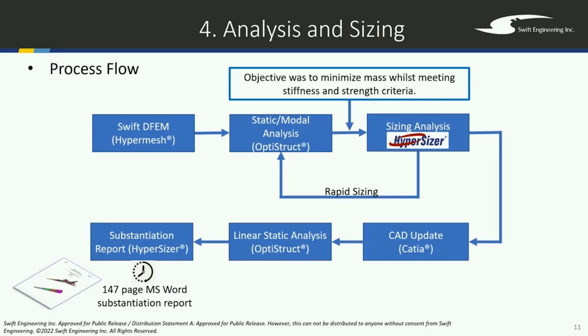We just had one workstation, 20 core, 256 gigabytes of RAM, and had we done it in any other software like Altair's OptiStruct, I think that would have been one of our roadblocks, that we might not be able to get optimizations turned around in quick enough time. This thing within 20 minutes gave me a result to say, hey, yes, you can change, apply, or no, don't apply. These are the margins.